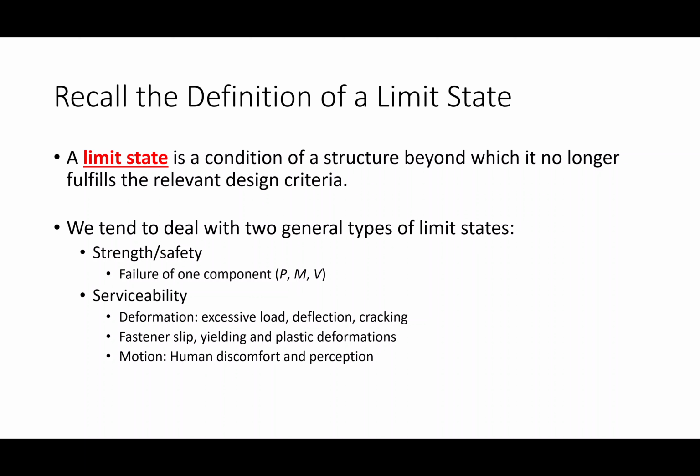Well, what's happening in the can is that when you take that element and you cycle it back and forth, you are introducing micro cracks into the metal right there. As you're doing that, you're cracking the metal, separating it ever so slowly. And it is a function of the cycles that you apply. The more cycles you apply, suddenly it gets weaker and weaker and weaker, and at the very end, it just sort of falls off, okay?